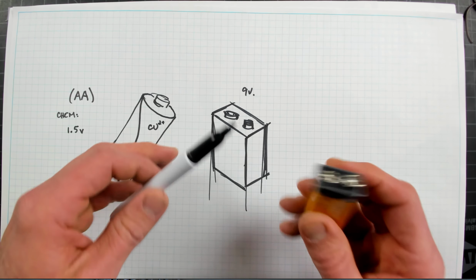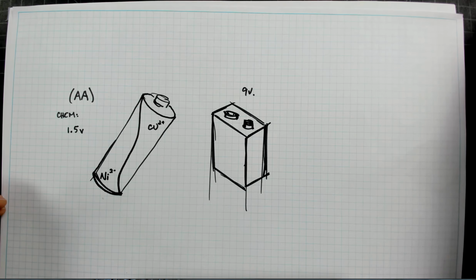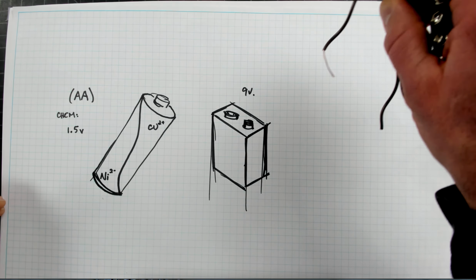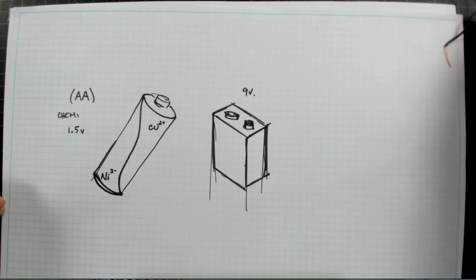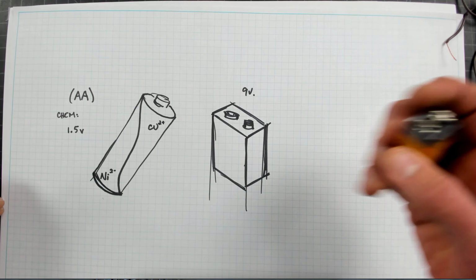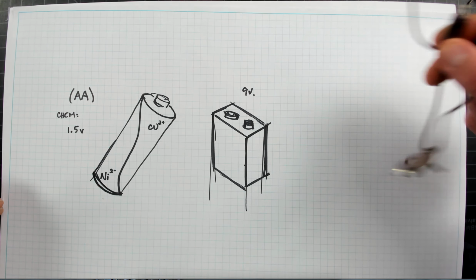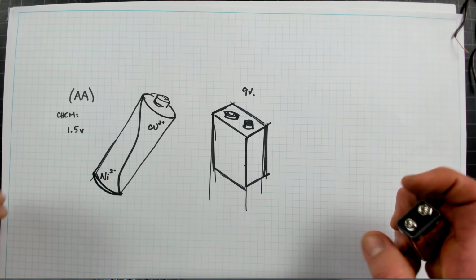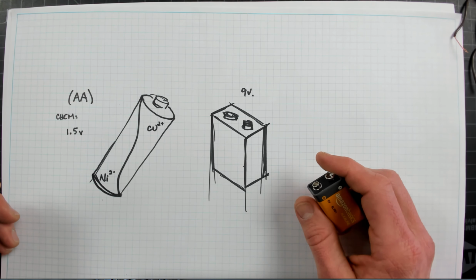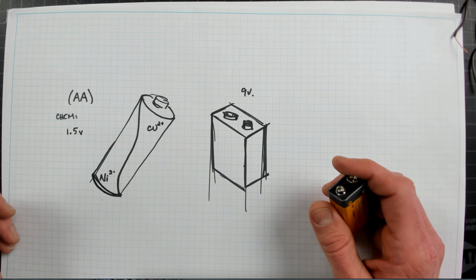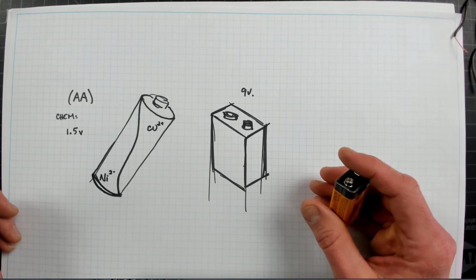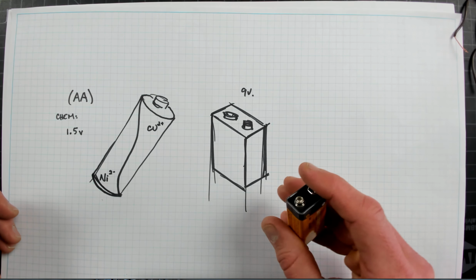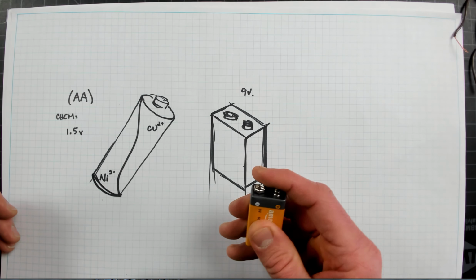But in the configuration that we're working with, we're going to be doing our parallel circuits with AAs. If you were to move up to 9 volts, you could still figure it out, but you would probably be running a couple of your LEDs in series. We're not concerned with that for the design challenge. All we're worried about is a parallel circuit with AA batteries. We want to make sure everybody is self-confident when it comes to the dangers, where you're safe, what's dangerous.